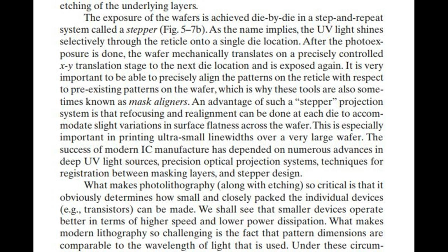The exposure of the wafers is achieved die by die in a step and repeat system called a stepper, Fig 5.7b. As the name implies, the ultraviolet light shines selectively through the reticle onto a single die location. After the photo exposure is done, the wafer mechanically translates on a precisely controlled XY translation stage to the next die location and is exposed again.